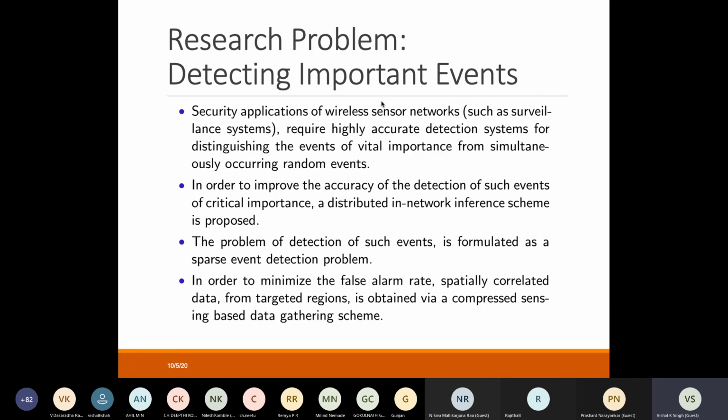What will be the case of an anomaly? The anomaly will be that, let us say the event is being reported in 5 frames: the first frame, second frame, third frame, fourth frame, and fifth frame. Now the persistence period is 5 frames. However, the event was reported in the first, second, and third frames, but not in the fourth and fifth frame. Let us say if the event occurs, it will be reported as 1, and if it does not, it will be reported as 0.